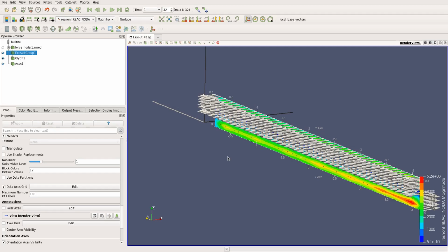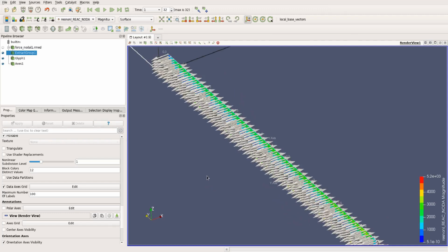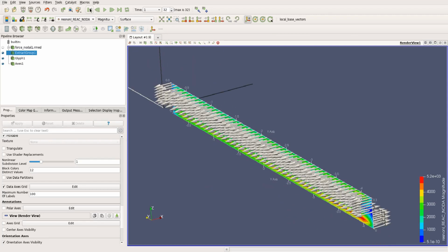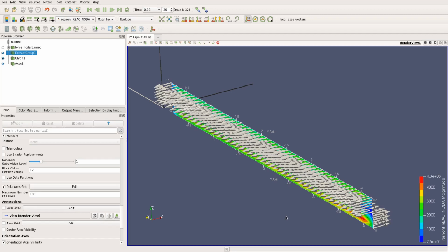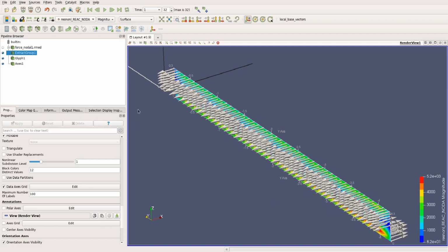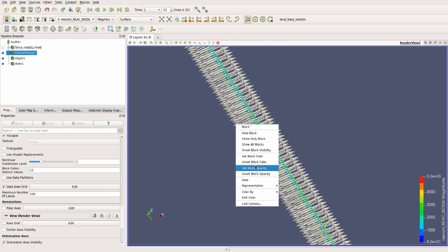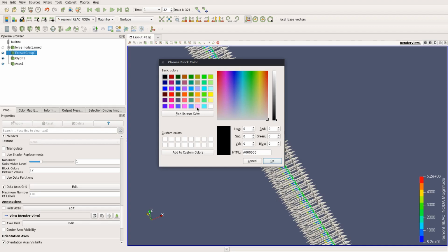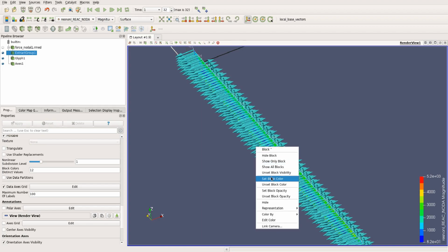Now this is my nodal reactions. Of course, I can see them updating through the entire simulation. If I go back to my start, it's oriented in this way, but the values are very small, so it doesn't matter. So you can see the values getting updated, as well as the orientation. I can just change the color over here also to set block color. Choose sand. Okay, it's good. So that is my nodal reactions.